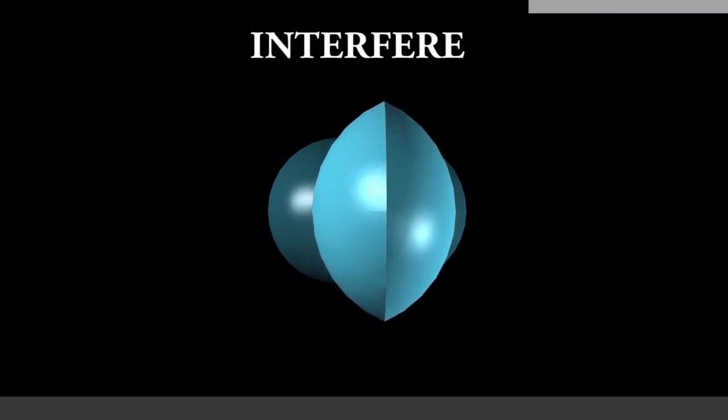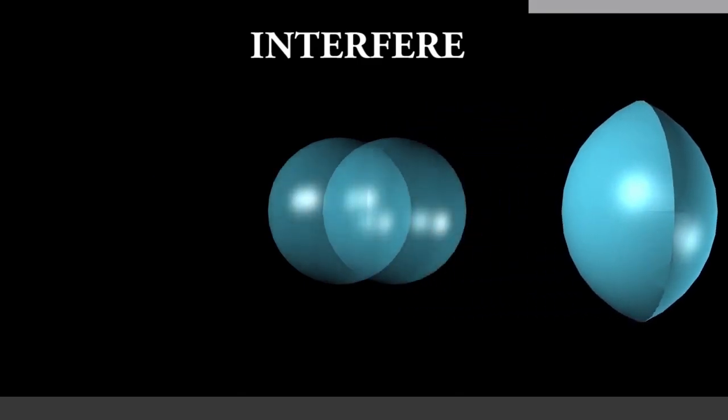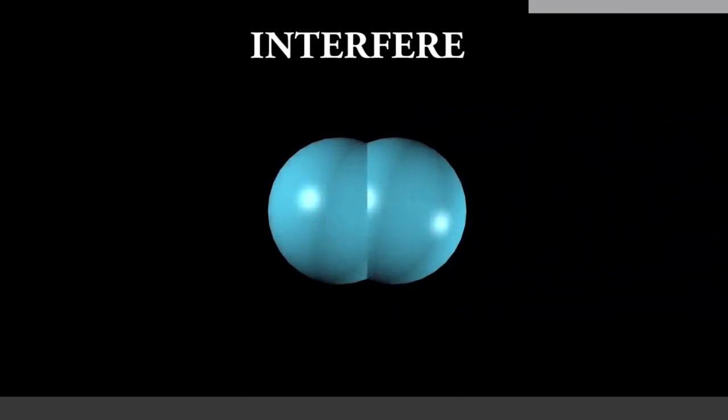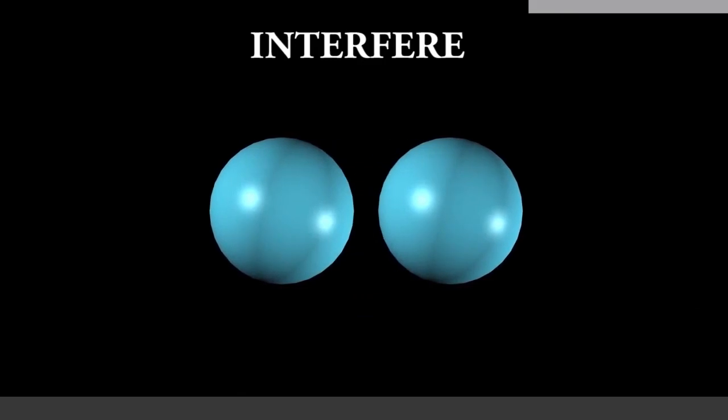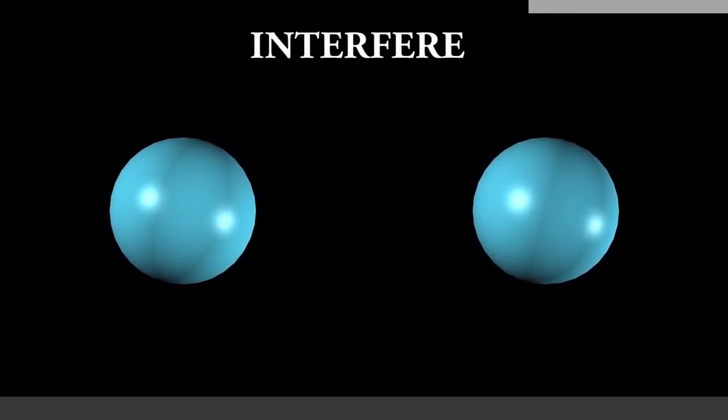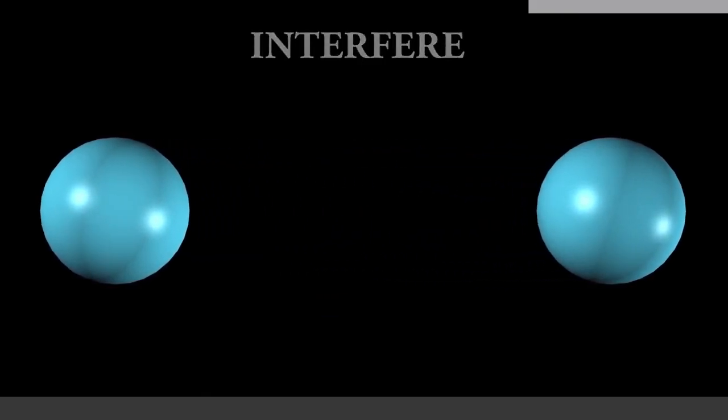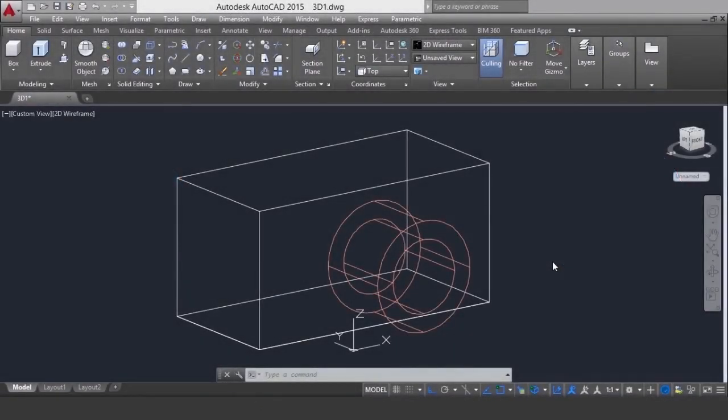The software divides the solid objects taking part in this operation into two sets of solids. After selecting the first set, we can give an enter, then you can go for the second set. Let's come back to our model. Now you know what is meant by subtraction.